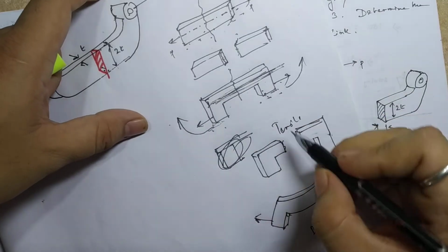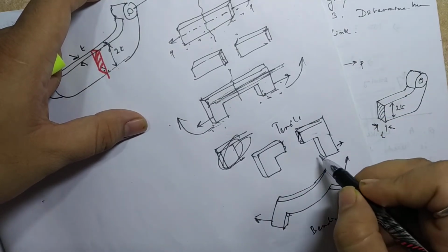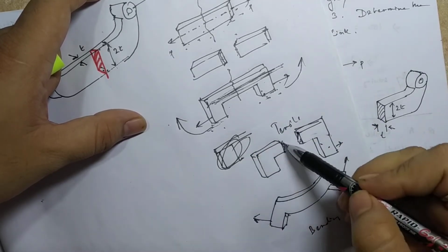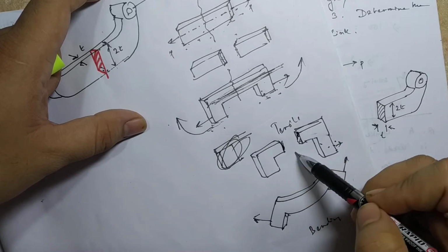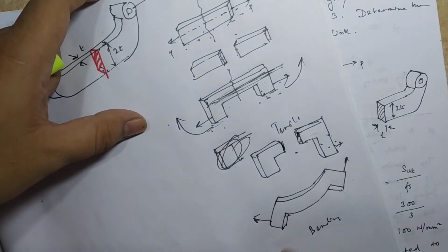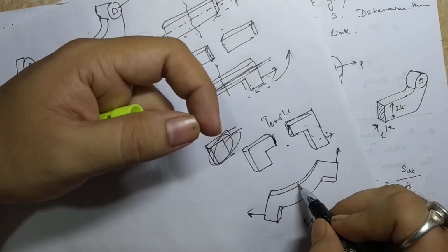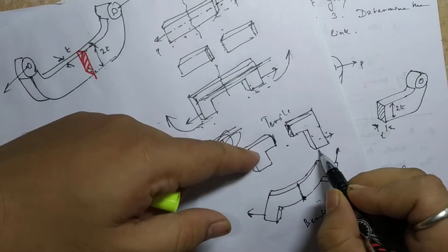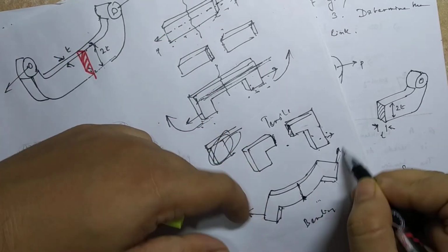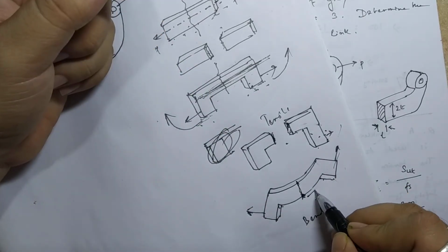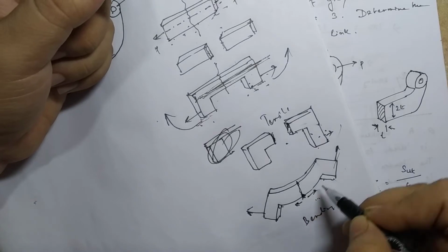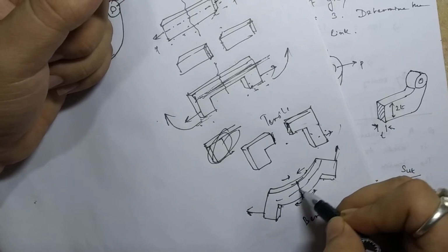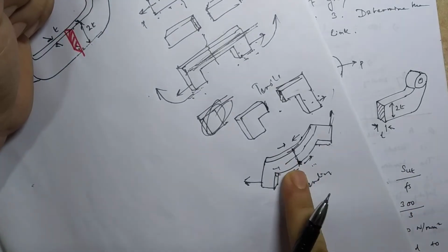Why tensile? Because your failure area here is perpendicular to the force. This is the direction of the force, so your area is perpendicular to the force. So this is the tensile failure. Here this is a bending failure, because if it bends like this and ultimately breaks, it will start shearing from this point and break here. So this is not because of tensile, this is due to bending. Here maximum tension is experienced, at this surface maximum compression is experienced, and between them there is an axis called the neutral axis. All these things are from strength of materials concepts.